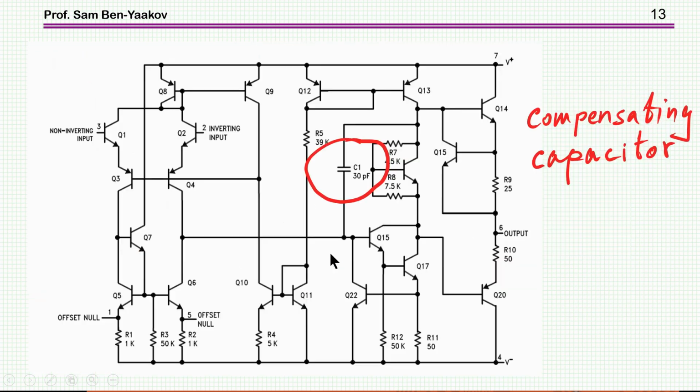The difference being that in the case of the amplifier, you have this capacitor, and I'm talking about an internally compensated operation amplifier. Now, the purpose of this capacitor is to stabilize the system, because without the capacitor, there's too much phase shift, too much lagging, and it'll be almost impossible to close the loop from outside and stabilize the system. So all the vendors today are providing an internally compensated amplifier, which has this compensating capacitor.